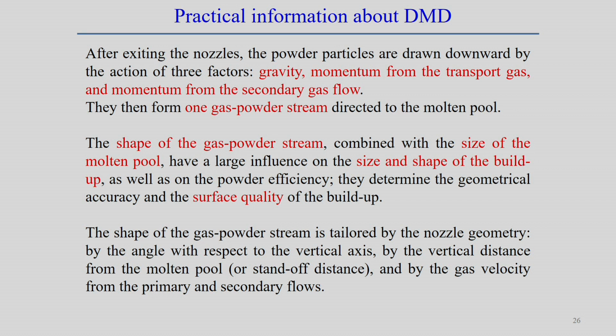But some practical information about the direct metal deposition techniques is maybe useful when you try to develop some kind of metallic printer. So, first, existing the nozzle, the powder particles are drawn downward due to the action of the 3 factors. So, physically the gravity force is important, and the momentum from the transport gas, because the powder is not carried just only by gravity, because there is some transport gas mixed with the powder, such that this transport gas actually carries the powder to the desired position.